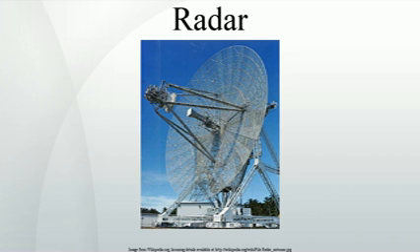Pulse Doppler signal processing. Pulse Doppler signal processing includes frequency filtering in the detection process. The space between each transmit pulse is divided into range cells or range gates. Each cell is filtered independently, much like the process used by a spectrum analyzer to produce the display showing different frequencies. Each different distance produces a different spectrum. These spectra are used to perform the detection process. This is required to achieve acceptable performance in hostile environments involving weather, terrain, and electronic countermeasures.